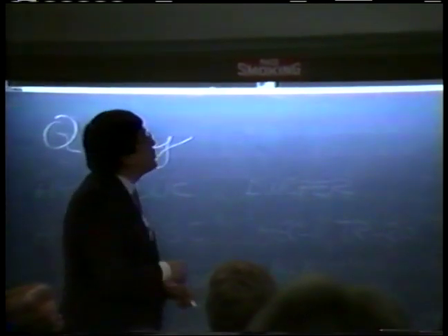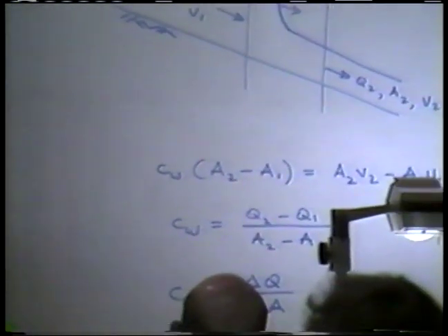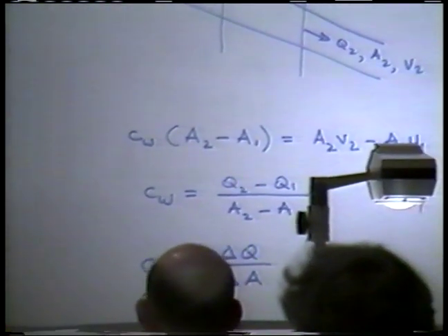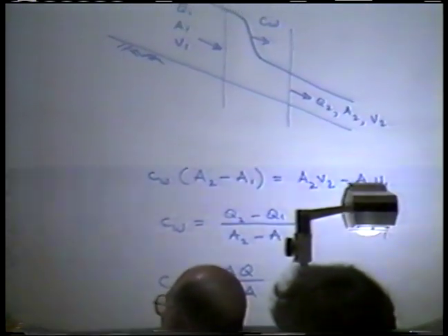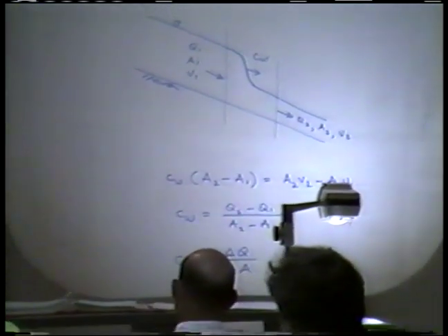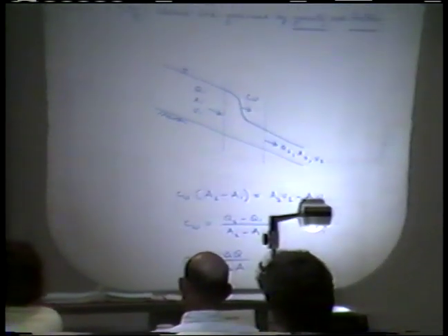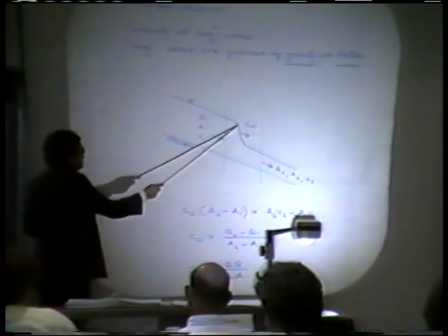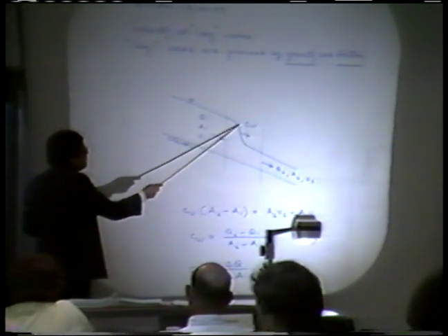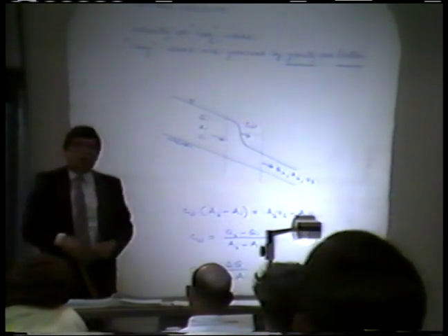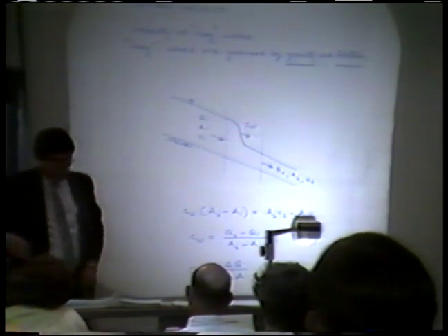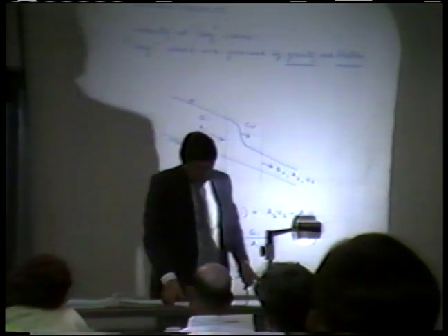And in fact, when Cho talked about the monoclinal wave, he was actually referring to this velocity, which, earlier by Lighthill and Whitham and later by several other people, has been identified as being the celerity of the so-called kinematic wave. We will have a chance to talk about that later on, when I talk about the kinematic shock, as to how locally these individual parts of the wave can differ from each other in terms of the velocity or the relative celerity that they have. But we'll talk about that later.